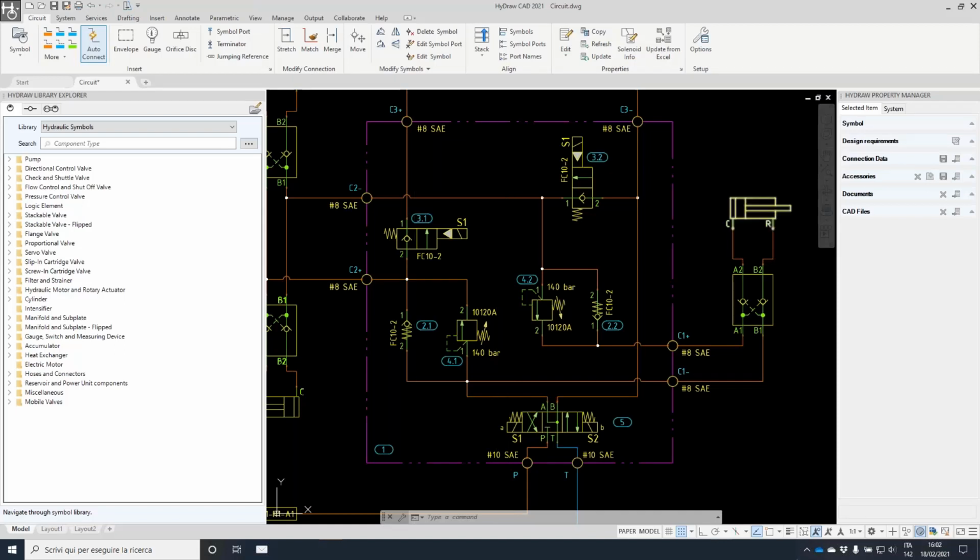When we look at the diagram, if we design on paper, we need to read our schematic. This kind of mobile manifold usually is a bit complicated because, as we see here, we have a net. We need to make sure to connect port 2 of item 2.2, port 1 of this item, port 1 of this item, and port C2 minus. For HyDraw, this is called a net, and the same concept is applied to MDTools.